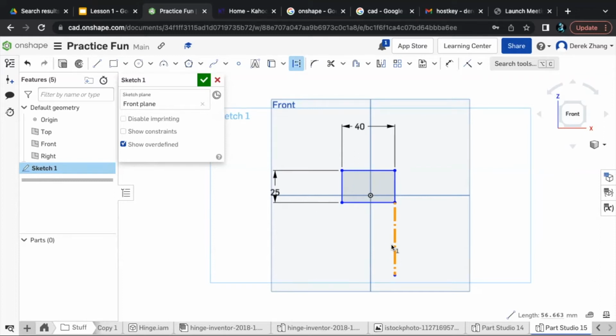All right, does everyone have a rectangle that's dimensioned with a construction line that's coming downwards? The thing with these construction lines is that the 3D printer doesn't see them. They're basically invisible. They're just to help guide where you're drawing things. But when you actually print, if you have all construction lines, nothing's going to print. So make sure you have the straight lines if you want to print something out.